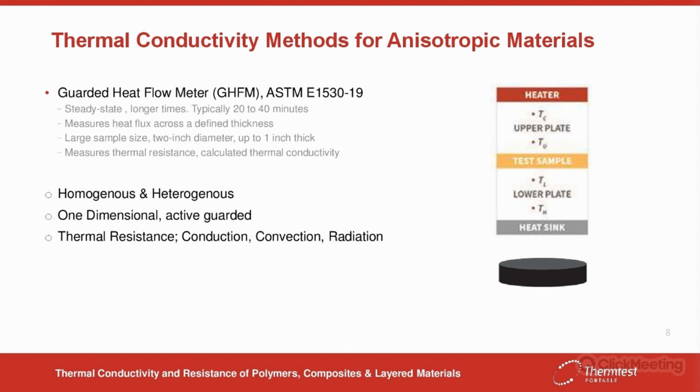The typical sample size is 2 inch diameter, that's fixed. The thickness can vary up to 1 inch thick, so you can do different thicknesses based off of that standard 2 inch diameter. It does measure thermal resistance, and from the known conductivity, the method calculates thermal conductivity.